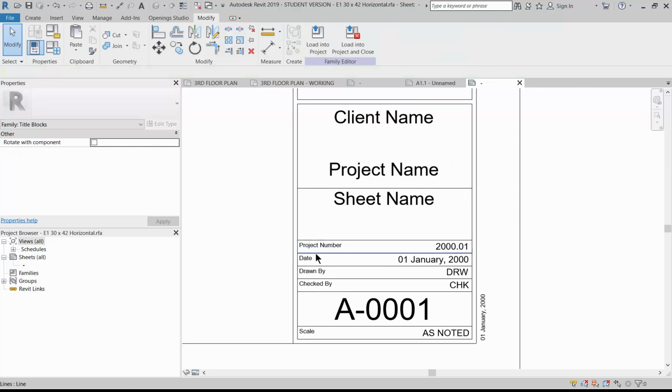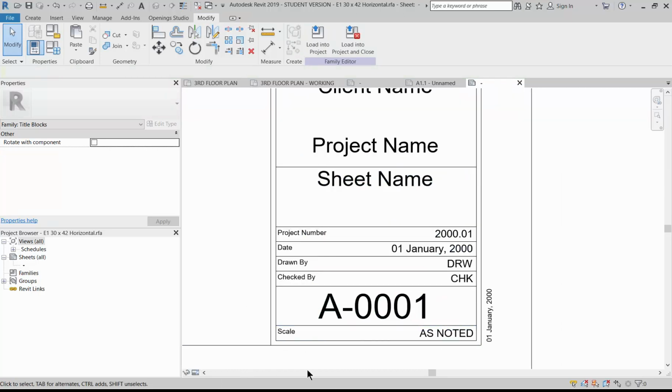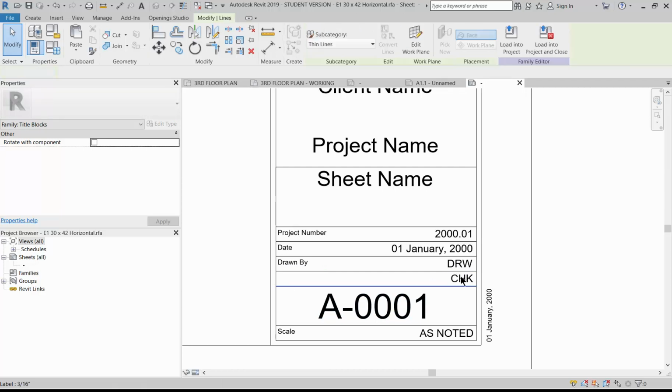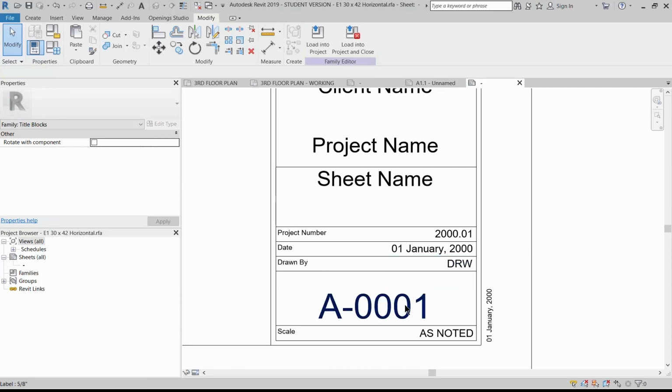Now if you have 11 by 17, you can use the scale in a title block. You usually only have one drawing on 11 by 17, but on a larger sheet we will often have multiple drawings. And then look at the other information. Now I appreciate that a lot of times you'll put my name under the checked by, but by the time you give me the drawing I usually won't check it, so we can get rid of that category.